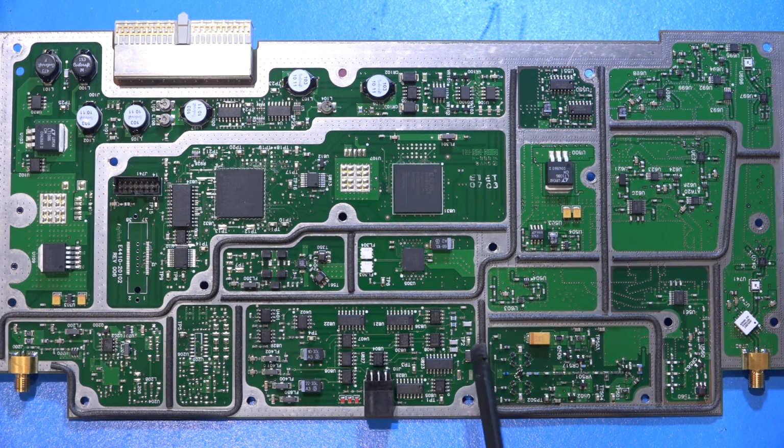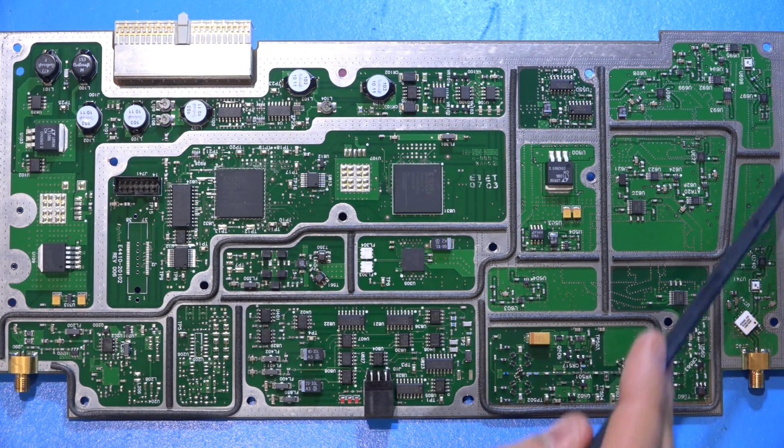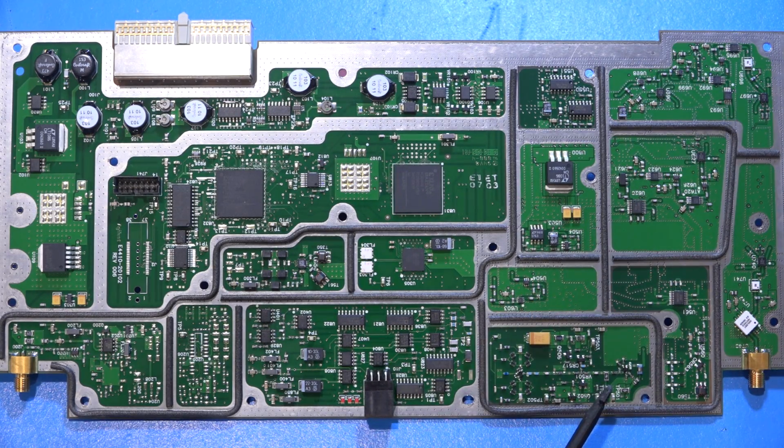So I am hoping that these signals are actually the same as the signals that control the VCO, which would be a huge help because we can measure the signals that control the varactors on the VCO, and we can see if the PLL is doing what it's supposed to do. At the same time, we can monitor the output and see which frequencies it is showing, and that tells us something about the functionality of everything else. There's really hundreds of things you can test here.